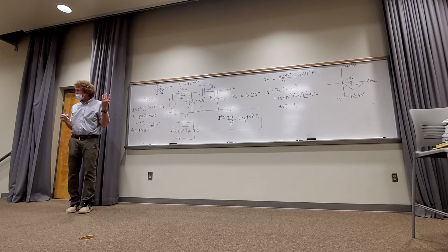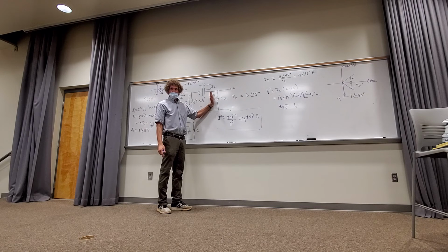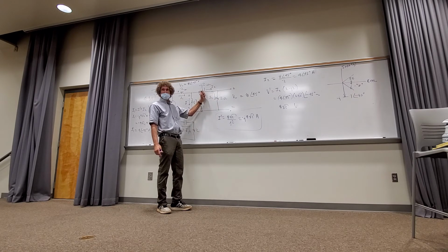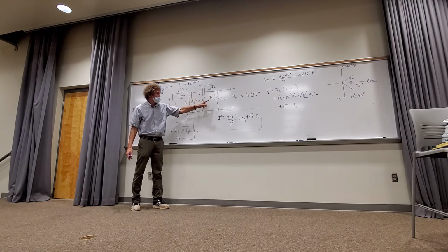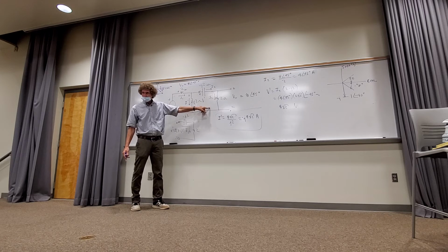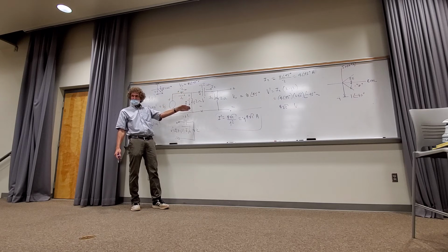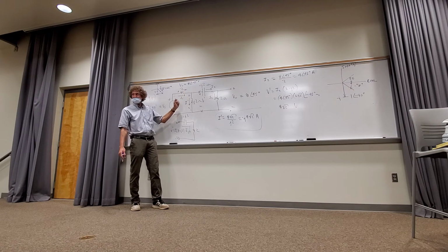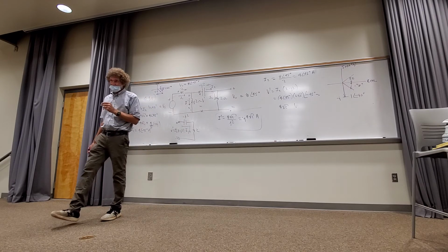And I've worked backwards and sequentially got everything I didn't know. From here, I got the current flowing through there, so I got the current here, right? From the current here, I got this voltage because that current was multiplying these 2 impedances in series, and I could get that voltage. From this voltage, I got the current right there through J2, and once I had that current, I added that current in I2 to get this current, right? Once I had that current, I multiplied it by 2 to get this voltage, and I added this voltage to get VS. And that's it.